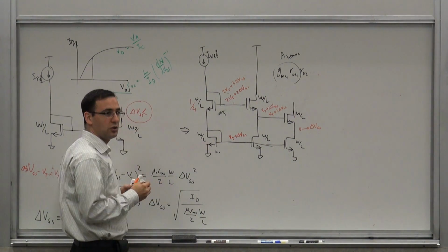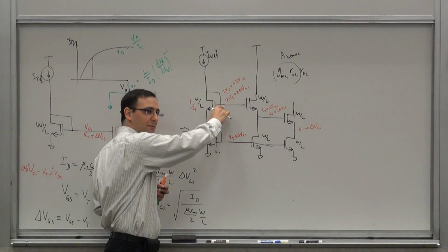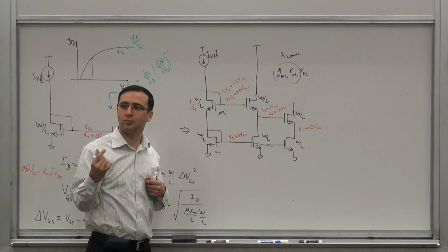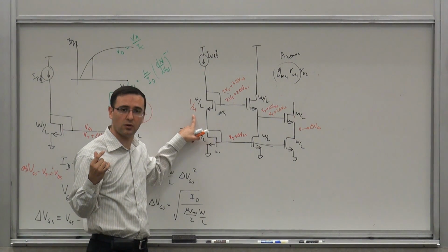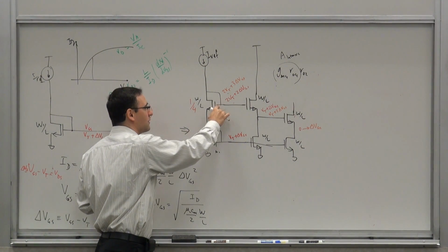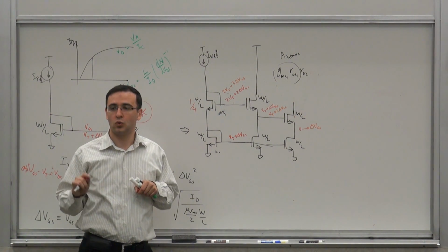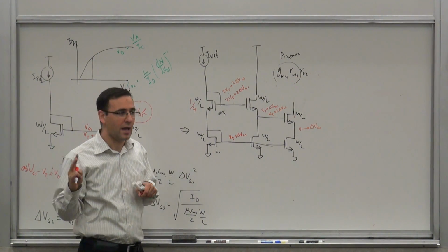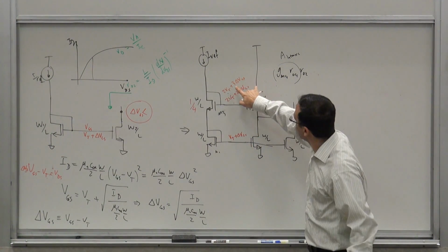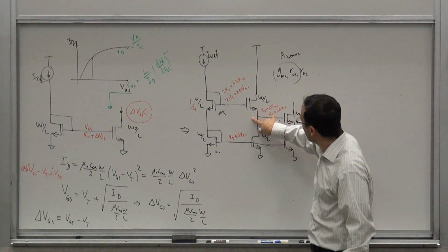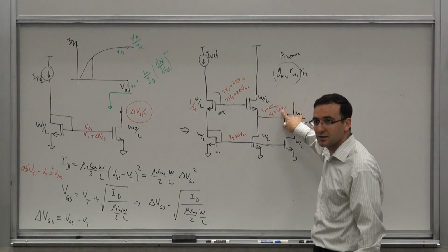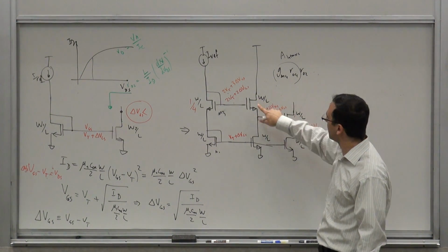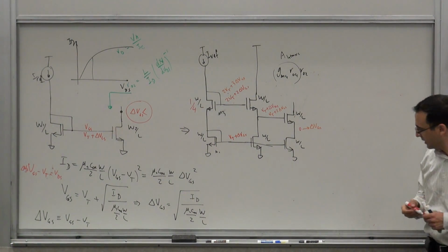So if I make this 1/4, do you agree that this voltage drop would be VT plus 2 delta VGS, the old delta VGS, twice the old delta? Making this a quarter, I've made the necessary gate overdrive at that current, I basically double the gate overdrive. Right? And then if I do that, the rest works out, because this becomes 2 VT plus 3 delta VGS, there's a drop here, this becomes VT plus 2 delta VGS, there's a VT plus delta VGS drop, and then therefore the orange values will hold.